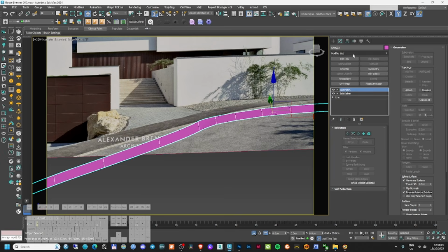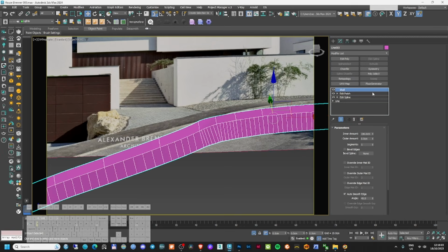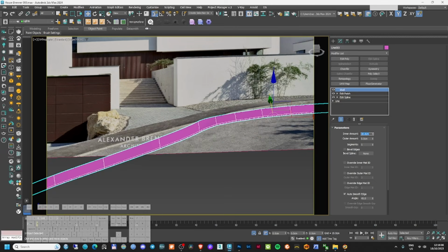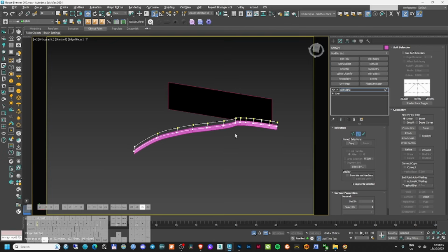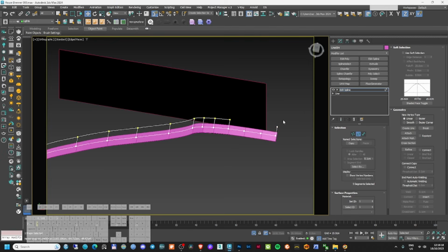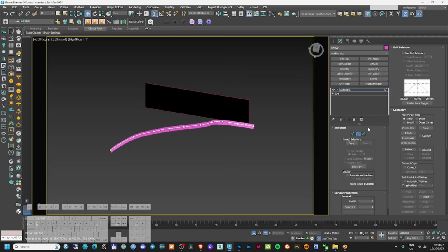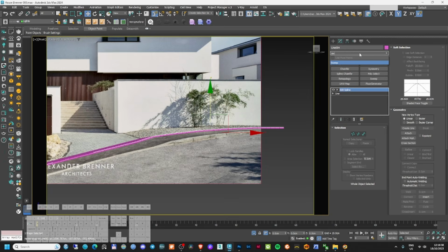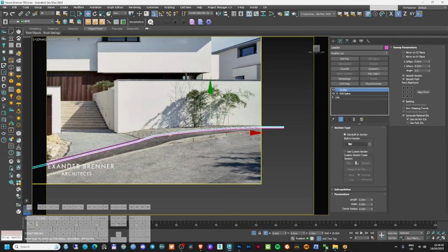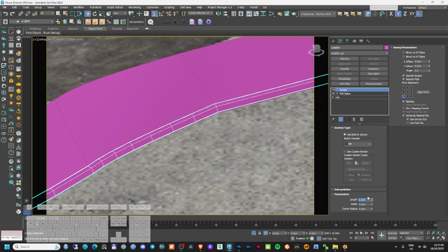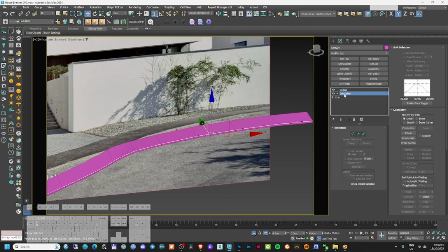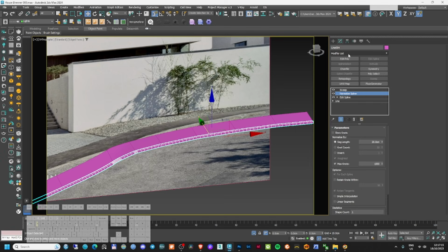Okay, and now this can also have a shell on top of it, so maybe not that big, then it should be enough. I can make a copy of this, delete all of this, then just start deleting. Sweep needs to be a bar, and this sweep can go, let's see where, and this can be 10 by 10. I can add a normalize spline in here, and the length of this can be 120 maybe.